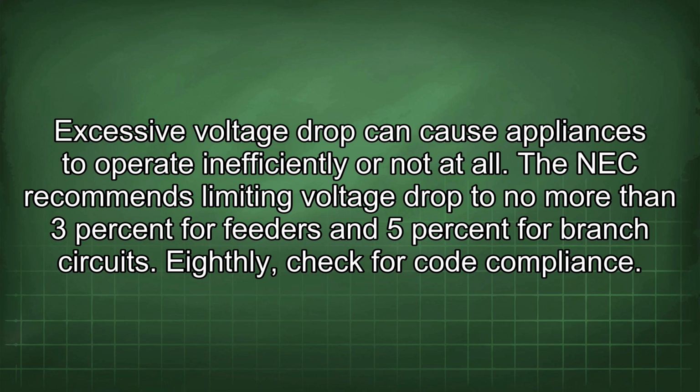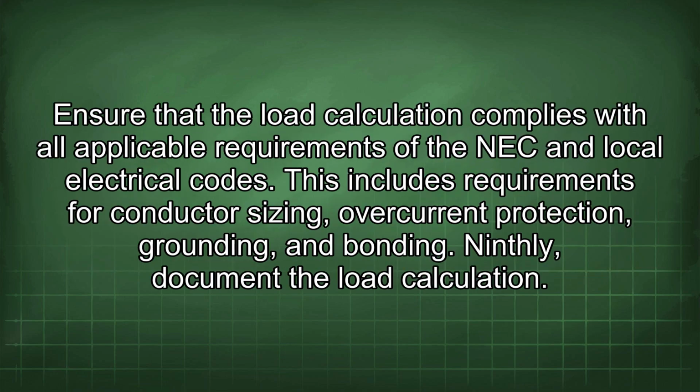Eighthly, check for code compliance. Ensure that the load calculation complies with all applicable requirements of the NEC and local electrical codes. This includes requirements for conductor sizing, overcurrent protection, grounding, and bonding.